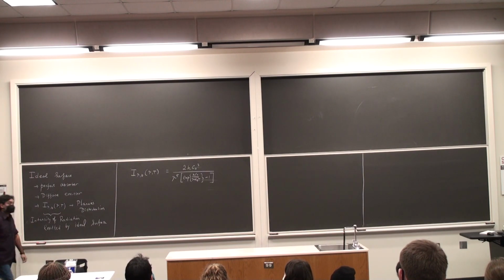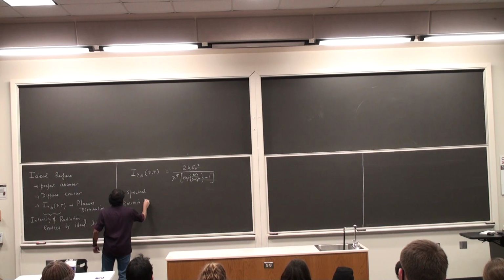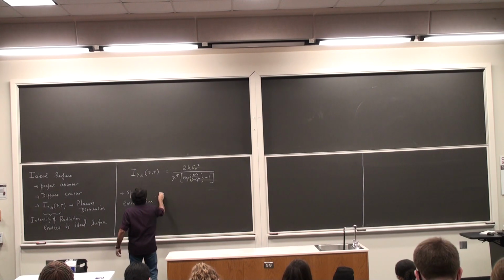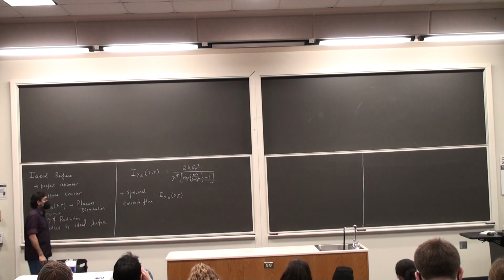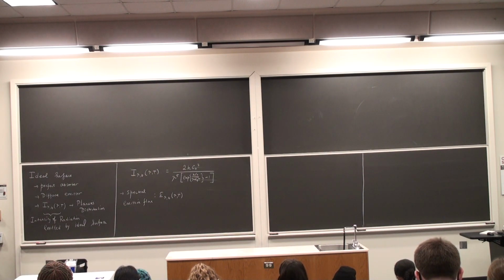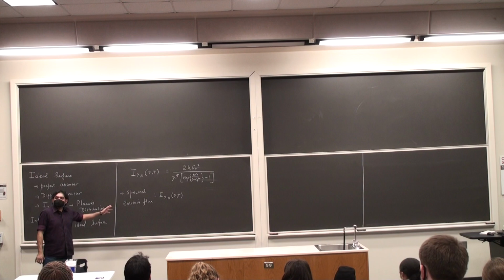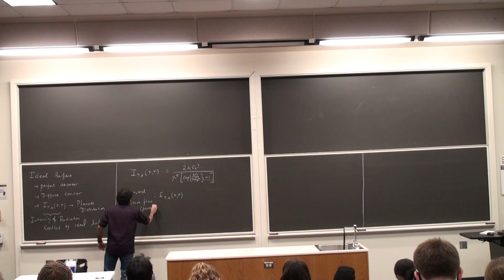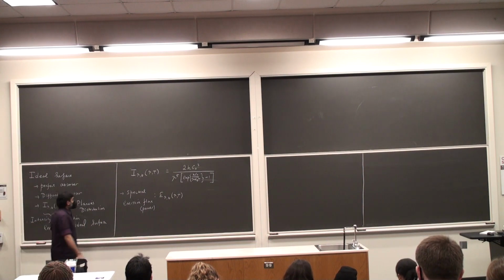Then we said that, because it's a diffuse emitter and so on, I can calculate the spectral emissive flux for an ideal surface. This is E of lambda comma b, capital E. Once again, a function of the wavelength and temperature. And please notice, this quantity is sometimes also called spectral emissive power, and the notion of power is power per unit area here. Okay? So this is also labeled as spectral emissive power in your textbook.